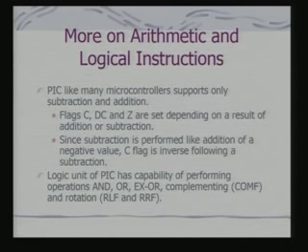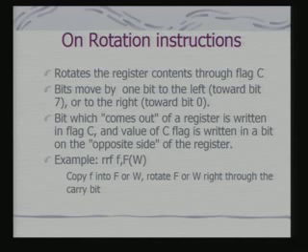The logic unit of PIC has the capability of performing operations like AND or XOR, complementing, as well as that of rotation, just like any other standard microprocessor or microcontroller. We shall look at rotation instructions. Now, typically a rotation instruction rotates a register content through the flag C. So, the carry flag is involved when we are doing the rotations. Bits move by one bit to the left or to the right, depending on whether you are doing a rotation left or rotation right instruction.